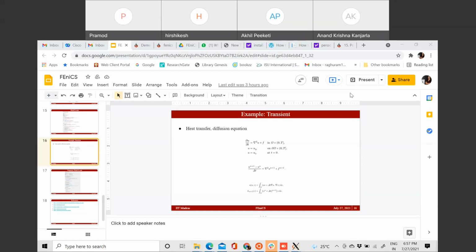Yes. So, Rishikesh, I was wondering, when you model this fracture in functionally graded materials, how do you then take care of this interfacial or cohesive kind of delamination or whatever? Actually, I have done it using phase field, so I don't need to care about the tracking of crack growth. The method automatically does that.